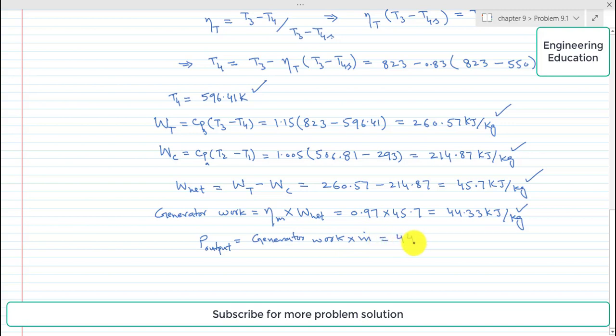So generator work is 44.33 kilojoule per kilogram into 15 kilogram per second. So the value of power output comes out 664.95 kilowatt. So this is the first part which was required to calculate.